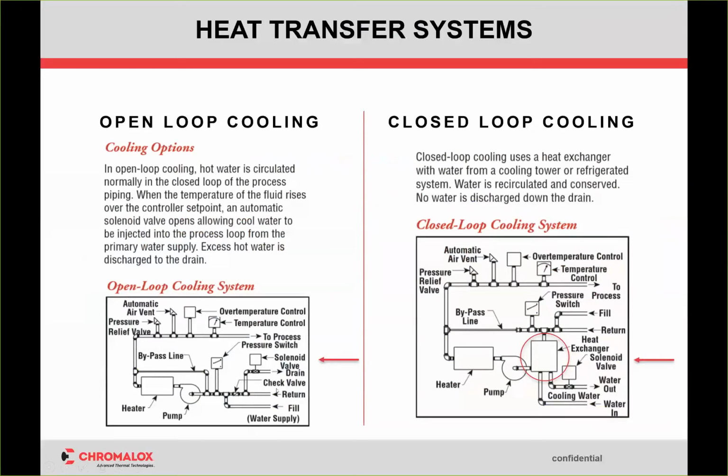But the open loop cooling is specifically, and you can see by the drawing, it illustrates it the best, you're actually adding, in most cases, water to an application. You could theoretically do it with heat transfer fluid, but then there's a whole containment issue. You're adding directly to the heating loop itself. In the case of water, that's easy: you're adding cooler water to the already hot water to temper it, and at the same time you're draining the excess, so you're not going to overload the system.